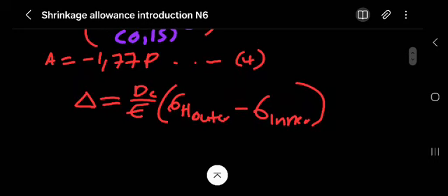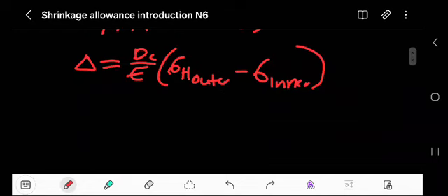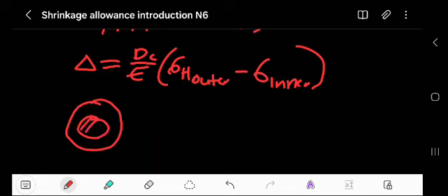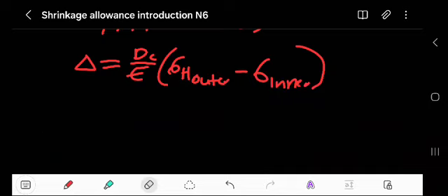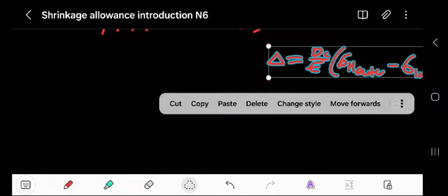All right, because you have to have the hoop stress. But the nice thing, this is a sleeve and a solid shaft. Remember, I've discussed this. At the contact diameter, the radial stress is equal to the hoop stress, which is also equal to the pressure. So we'll take advantage of that. Since we know this, let me just put this aside a little bit.